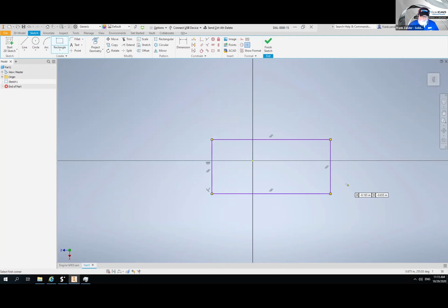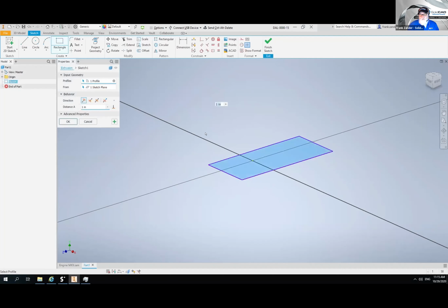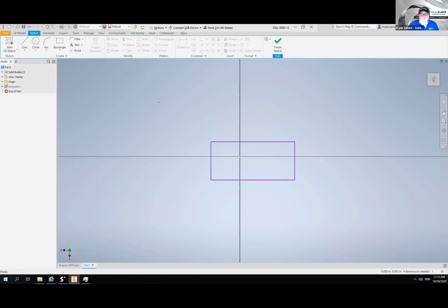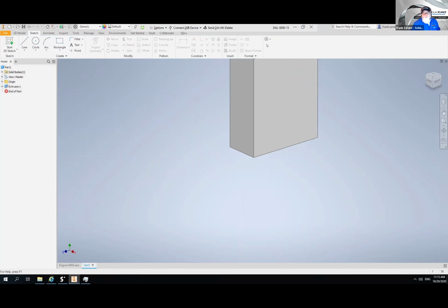You know, type the letter E for extrude, and we're extruding it, doing everything that you would normally do inside of Inventor, and boom, away we go. Start sketching on a surface. Create another rectangle. Do another extrude, and away we go. So this is how, very easy to use. Everything that you would do on your local machine, you can do in the cloud with SimpleCloud.